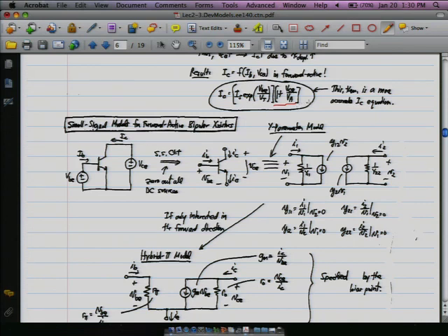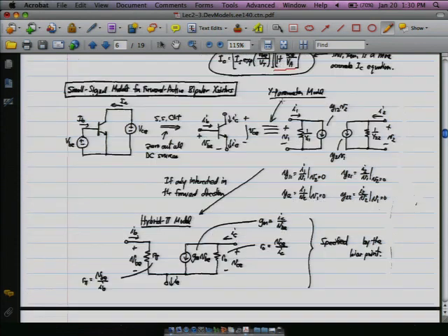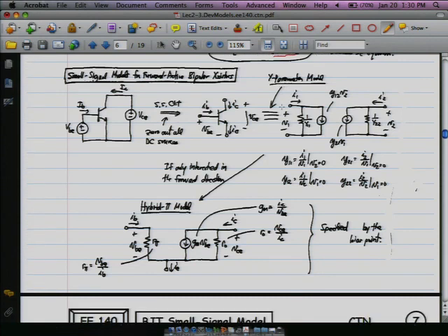All right, so this basically just says that the collector current has a VCE dependence. That's that. Okay. All right, so now we'll go a little bit further into the small signal models for the BJTs. The first model that's shown here is a fairly general two-port model. These models are very powerful because they're so general. You can express almost anything with them, and you'll actually see them more later in the course, to the point we start talking about feedback, because you can basically express more with them.